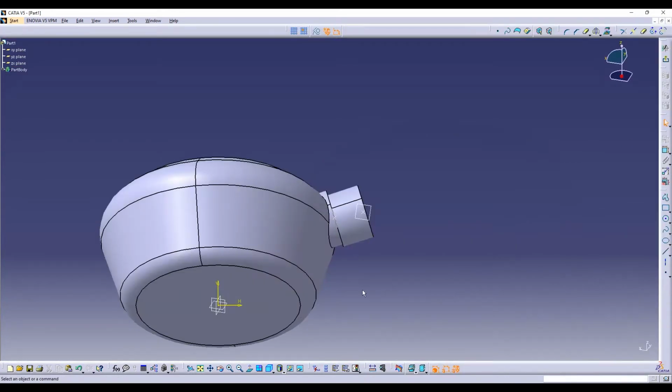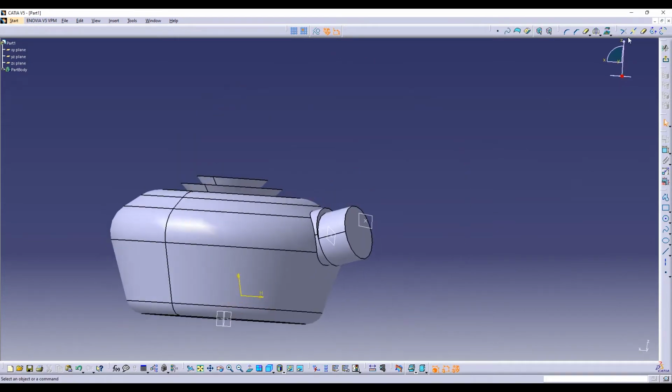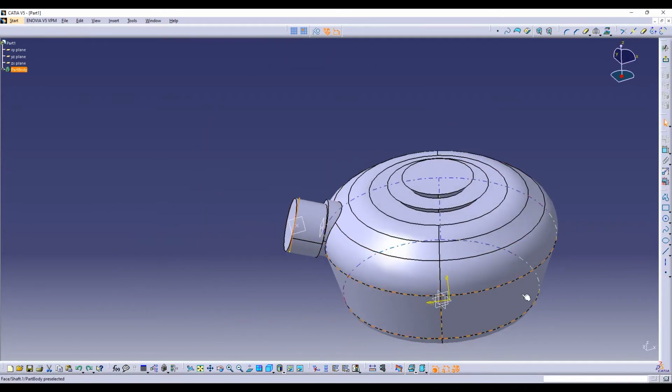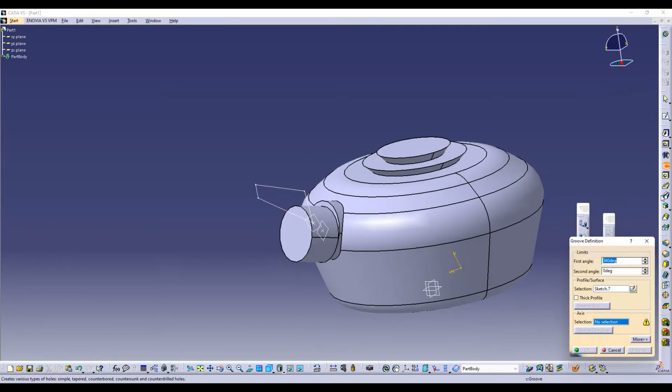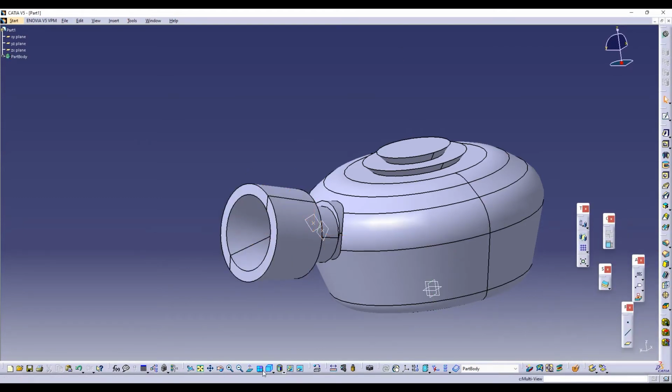Let's create an extra surface by the reference curve, by the reference plane we have taken. We'll try to create something conical-like structure here, and we'll revolve it. We'll draw a segment and we'll revolve it now, just like this. It's done. The 4 arms of the robot are created over here.